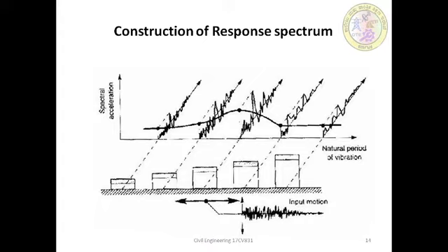The earthquake parameters such as soil conditions, epicentral distance, magnitude of the earthquake, duration, and the source characteristics influence the shape and amplitude of the response spectrum. While the effect of some parameters may be studied independently, the influence of several factors is interrelated, and it is difficult to consider them individually.